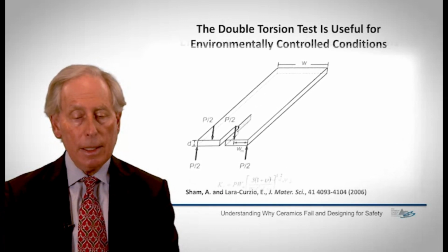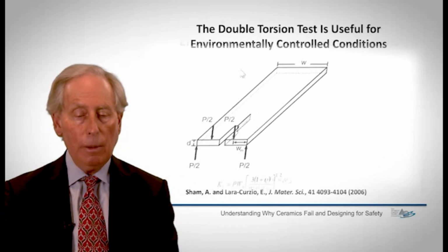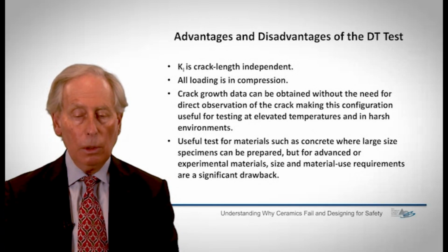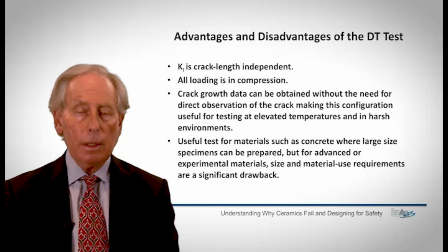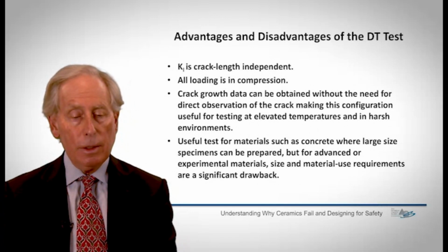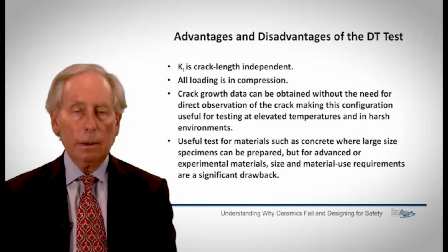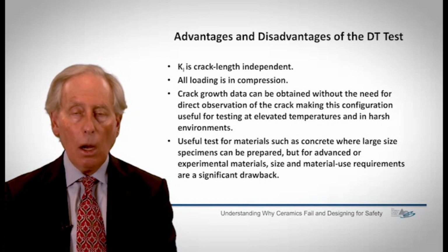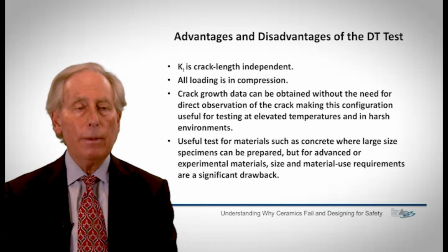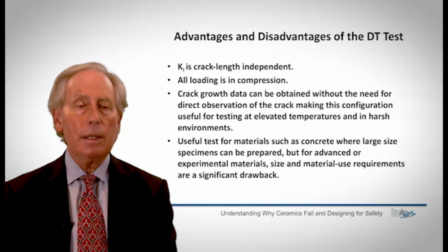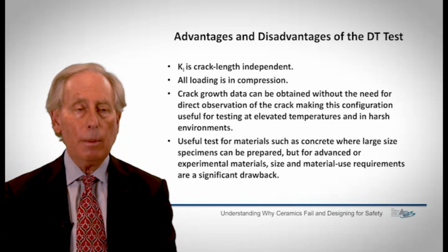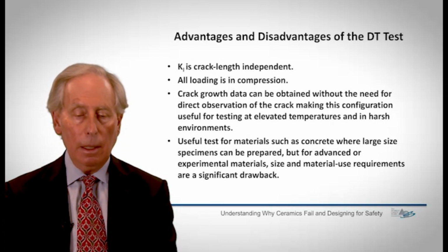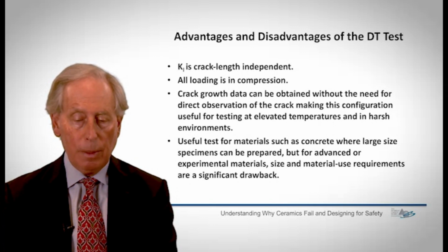And there's a very nice review of the double torsion specimen that I give the reference for here, and I would encourage you, if you want to use it, to go look at that. So, there are advantages and disadvantages. Again, stress intensity is crack length independent in this test, very useful in many applications. All loading is in compression. That makes it very easy to load up and do tests in an environment, or do tests at somewhat elevated temperature, because you don't have to attach anything to your specimen to get your data. A very nice feature of that particular specimen configuration.